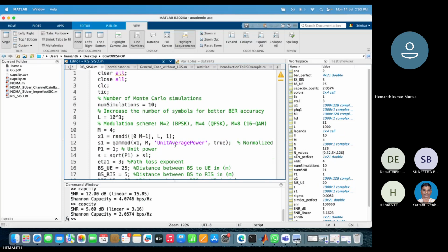Clear? See the code, everybody. First, what am I doing? I am doing the X generation. For X, I am using QPSK modulation. How did I generate it? M equal to 4. First I generate the initial bits. After that I pass them through the modulation function. That modulation with M equal to 4 generates QPSK modulation. What does QPSK mean? You know what the values of QPSK are? 1 by root 2, 1 by root 2. Don't know? Okay, I will show you here.